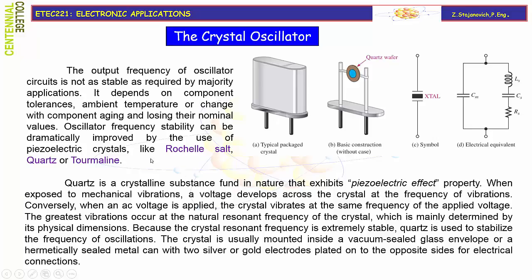When you compare Rochelle salt, quartz, and tourmaline with respect to the piezoelectric effect, it's interesting to say that Rochelle salt has the highest piezoelectric effect. That means that the vibrations have the highest amplitude for the same voltage, however it's very brittle. Tourmaline, on the other hand, is very robust and doesn't break, however it has a very low piezoelectric effect. So quartz will be some optimum selection with respect to how many vibrations we can get for a given voltage compared to the mechanical characteristics of the crystal itself.